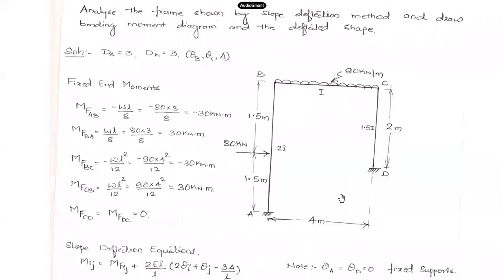What I have is two supports here which are fixed, three reactions over here, three reactions here, six unknown reactions totally, minus three conditions of equilibrium. That will tell you the degree of static indeterminacy. It is coming out to be 3.